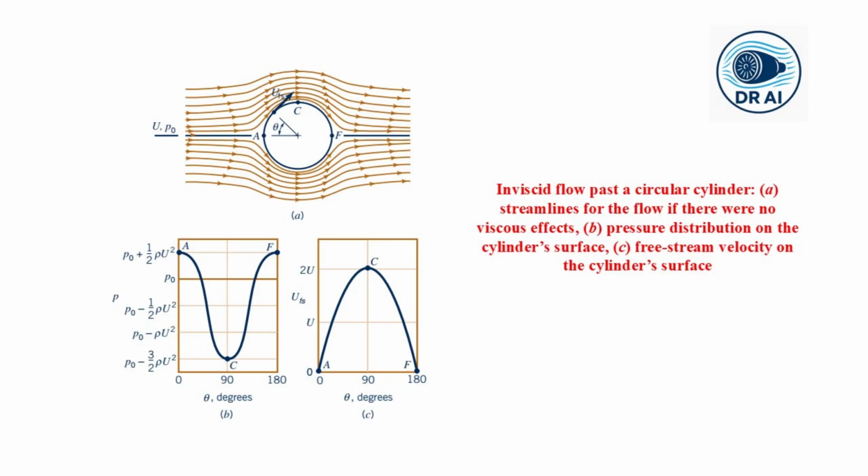And from the Bernoulli equation, the velocity changes and pressure changes as dP over dx relationship here. This pressure gradient is imposed on the boundary layer. Pressure is essentially constant across this thin boundary layer but varies along it. So consider inviscid flow past a circular cylinder.